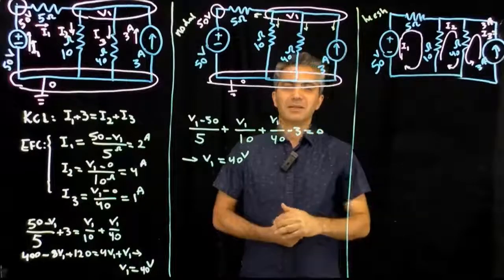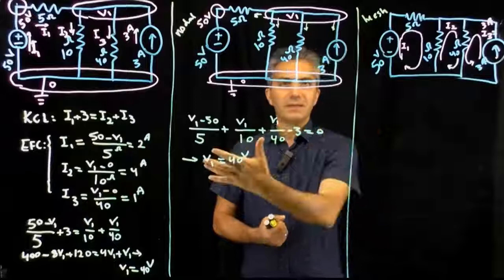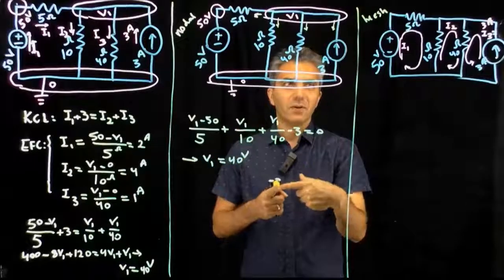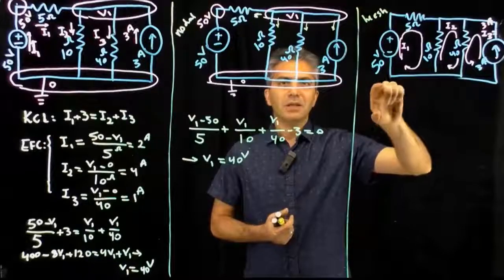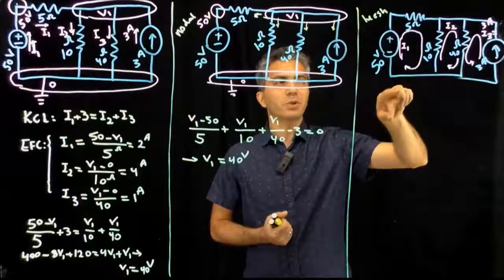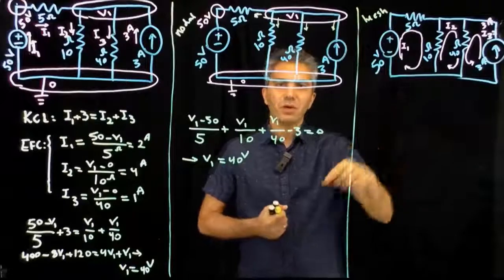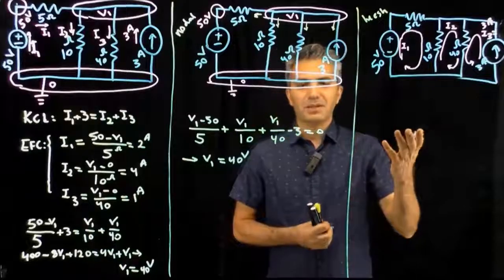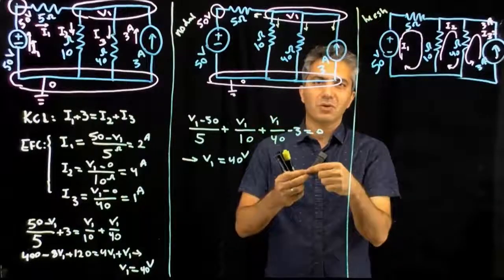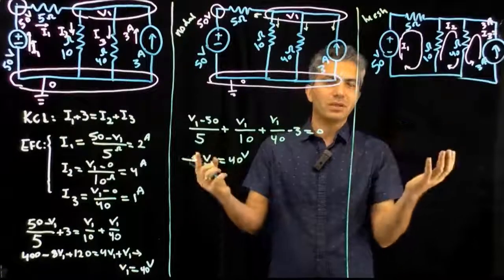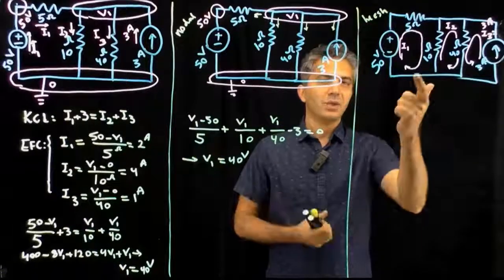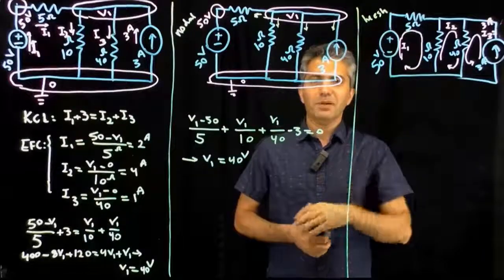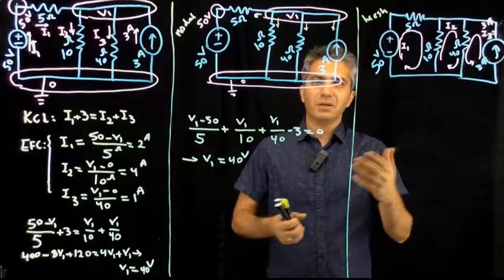So it's kind of a dual of KCL, but KCL was with electrons going in and out of a node. KVL is the dual of that with energy or potential when you go through a loop. With KCL we were saying that electrons don't generate out of nothing or disappear, and with potential, we say the energy doesn't generate out of nothing or disappear to nothing.